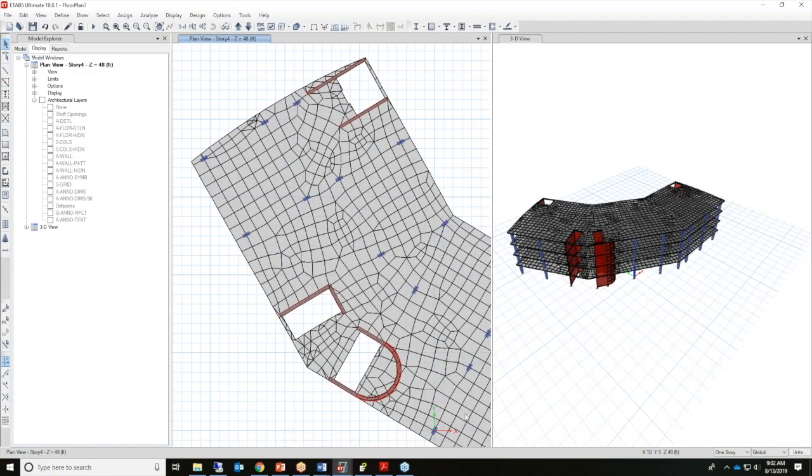Okay, so just a quick overview. So what is meshing? A mesh is a network of line elements and interconnecting nodes used to model a structural system and numerically solve its simulated behavior under applied loading. So in object-based modeling environments, engineers can generate structural models by drawing area objects that physically define the structure itself, such as wall panels, floors, and/or ramps.